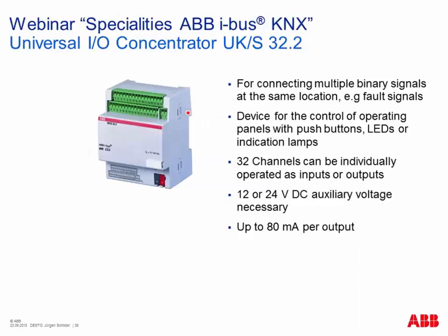And here a component not so often used and maybe not so well known, but still in use. It's a so-called universal I/O concentrator. What does it mean? In principle, it's a 32-channel component. Each channel can be programmed either as an input or also as an output. So very flexible and a lot of channels in one device. Typical application is to connect a lot of digital binary signals at the same location. For example, fault signals. Or a lot of buttons have to be connected here to such a device.